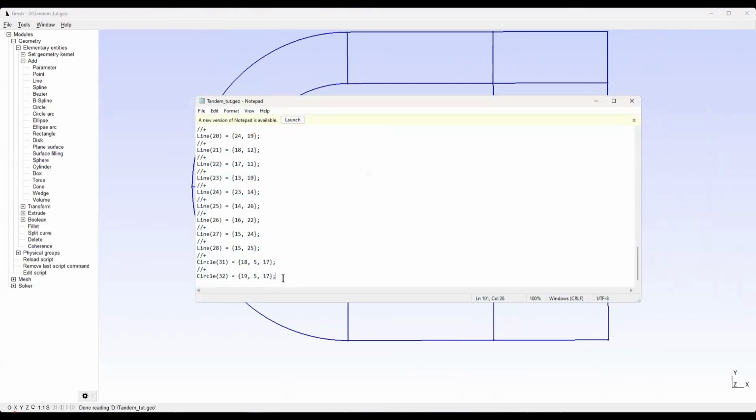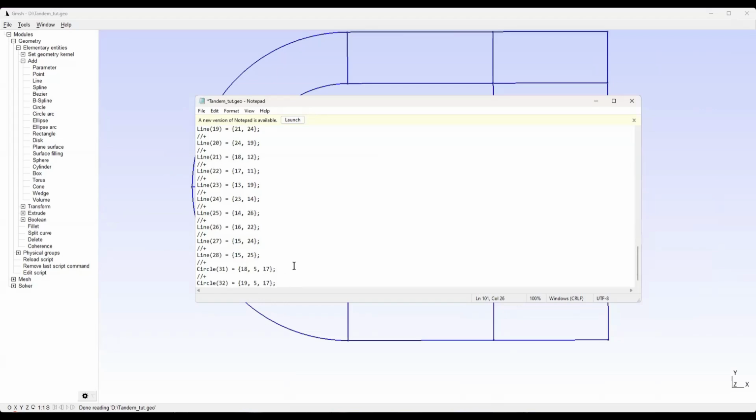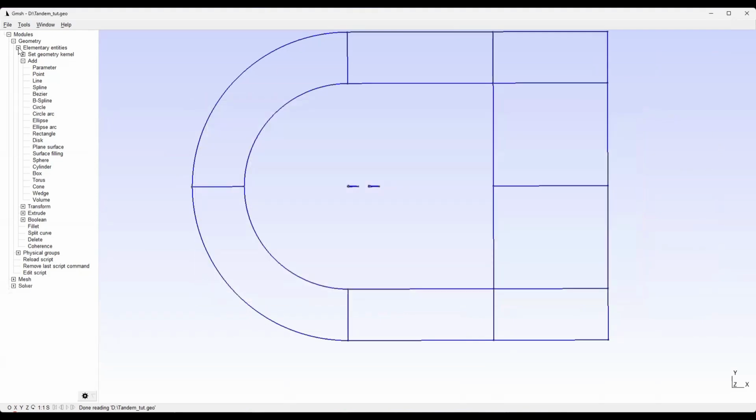I'm gonna make a title. Okay, making surfaces. We'll go element entities, add, and plane surface. So here's the select type boundary. So we're going to go ahead and do this. Doesn't matter which section you do, as long as they've all got surface, that's fine.